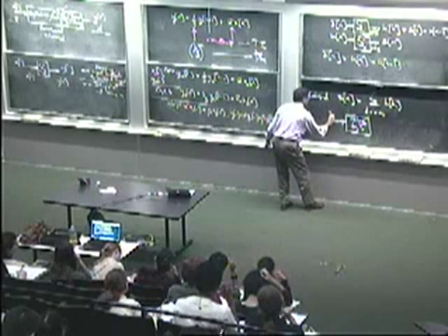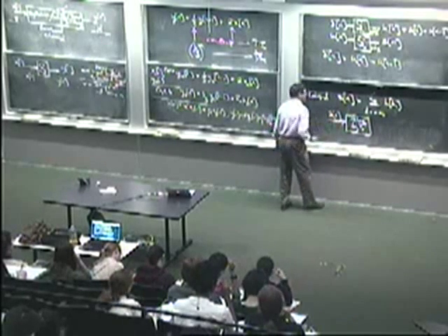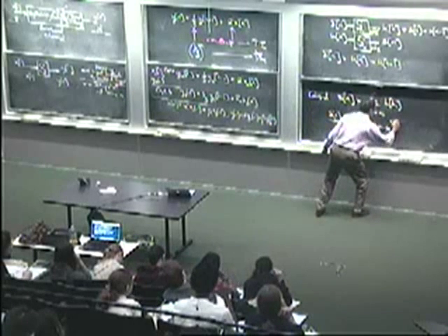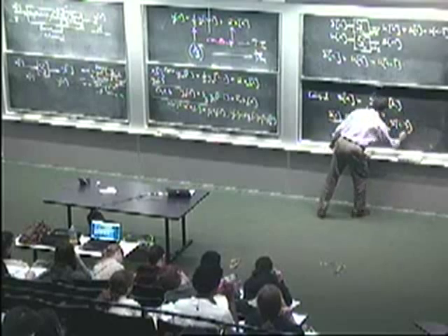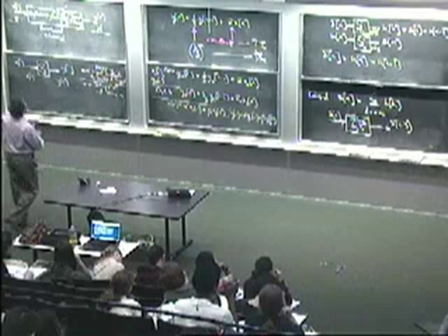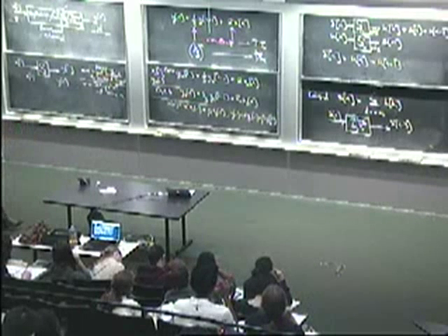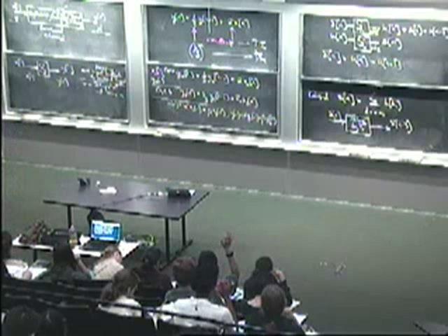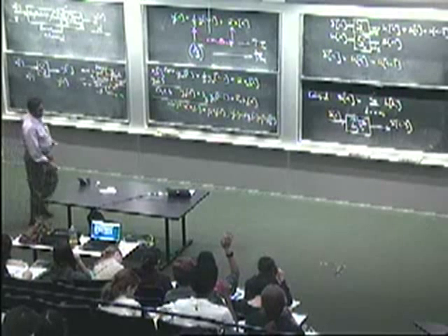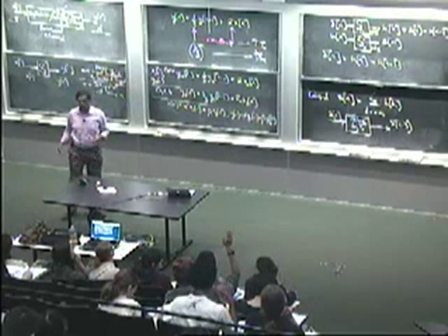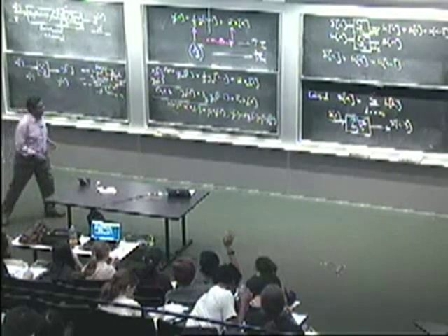Because we put in a unit sample input, a unit sample function, and what came out, if you look at it, was actually delta of n minus 3. It was a unit sample function delayed by 3 steps. The height is unchanged, right? The height is still 1. So this must be a delay by 3 system we're looking at. And sure, if we put in a unit step, we're going to get a response that's just the step delayed by 3. Okay?